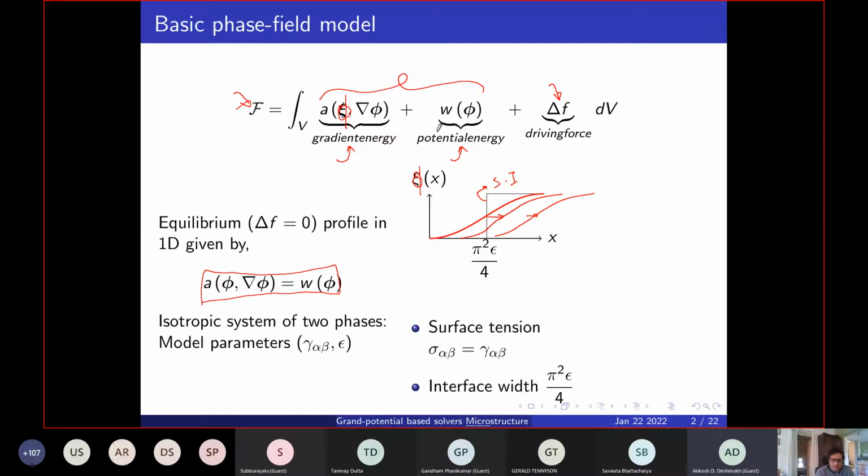Okay, so any phase field model that you can write down has two independent parameters, and you can tailor those depending on how you want to control the functional. One of the ways which is typically useful is to map the two independent parameters into the interfacial energy and the interface width. Okay, so you control these two parameters. There is another way. You don't need to directly control this. You can directly control the coefficient of the gradient energy term and the coefficient of the potential energy term, and thereby control these two parameters. But a natural choice is to choose the interfacial energy, which is the